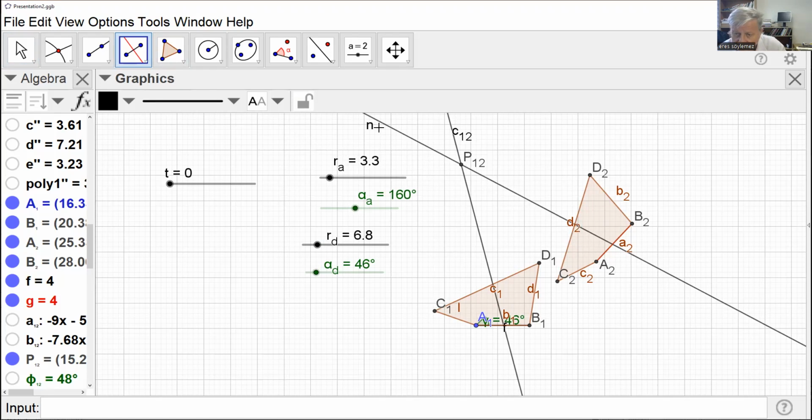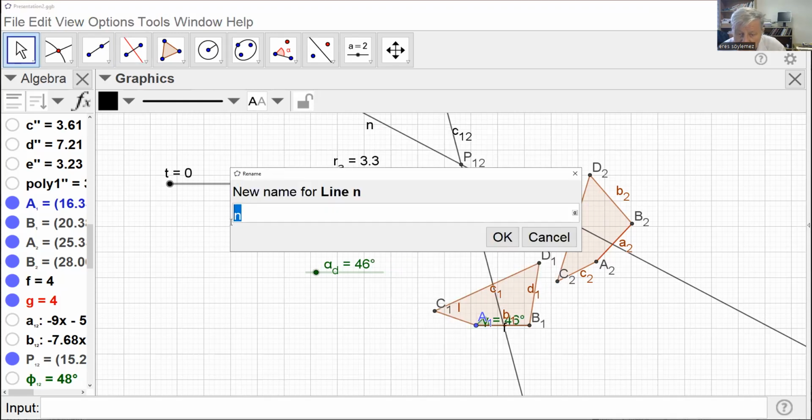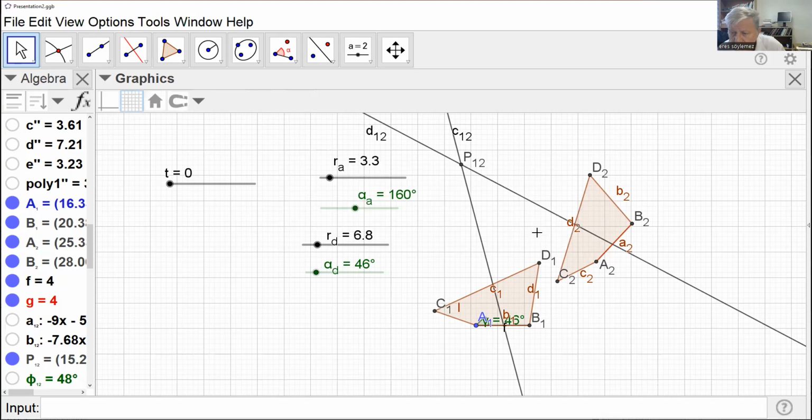Remember, we said that. This I will call D-1-2. Now, in order to select C0 and D0, they will be on these perpendicular bisectors. I have one additional parameter. I will use the link length CC0 and the link length DD0 as my parameters.